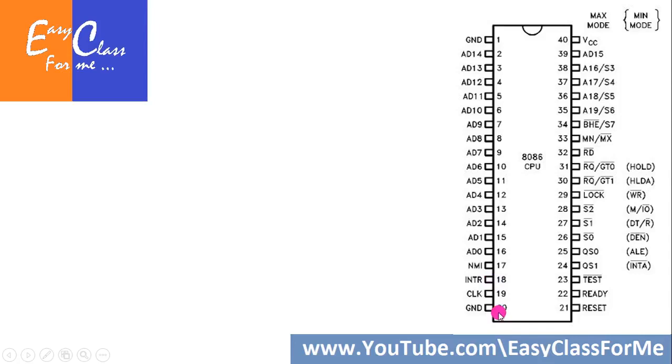So you can see on the left hand side we have seen almost all the pins: from 1, which is ground, then from 2 to the 16th pin we have the multiplexed address and data bus. Some portion of it is here also, and we have seen NMI, INTR, clock and ground. So the left hand side of this diagram is completely defined, and now we come to the right hand side. For the right hand side we have already discussed VCC, AD15, and these address lines. Now we will discuss the meaning of these status bits which are multiplexed with the 4 higher order address lines. So we will first come to S3 and S4.